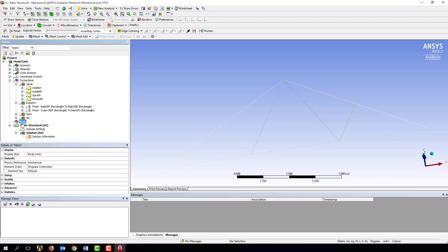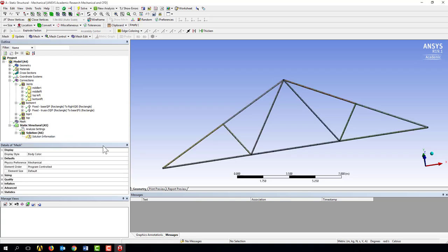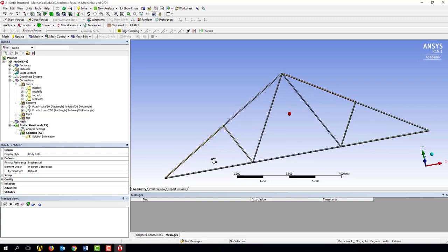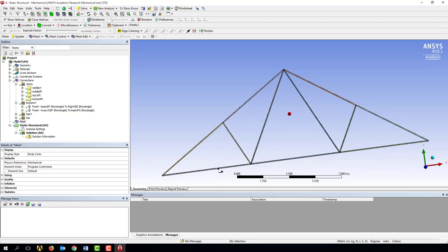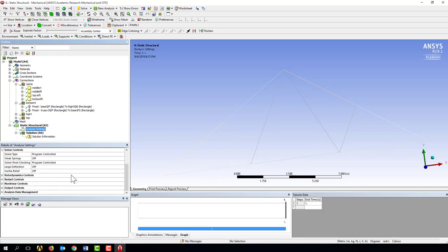The next step, if we go down there, is to create the mesh. So we can go ahead, if we right-click on there, we see that lightning mode, it means it needs to be generated. To generate the mesh, this meshes very quickly. For this type of mesh, it's not very sensitive to the number of elements. I'm just going to set that mesh and go forward, though generally we do want to take some care with our mesh. Now I can come down to analysis settings. These are parameters that may be set to help define the solution. And I see that my solution has question marks. There's a few things that need to be resolved.